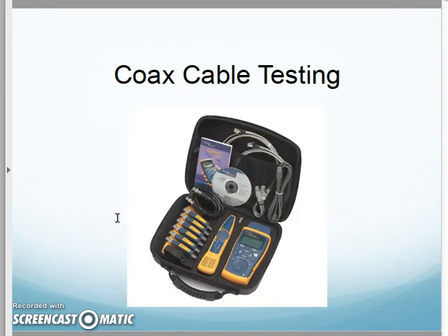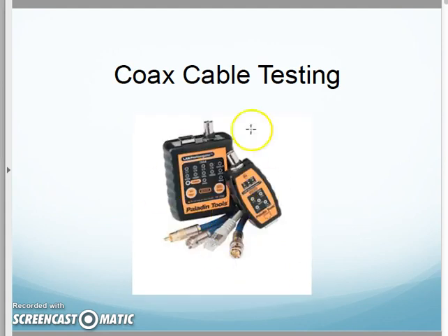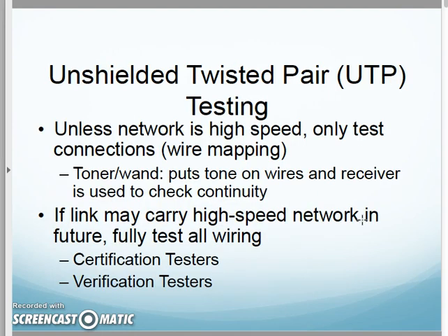The other thing we can do is there's actually meters, kind of like the wiremap meter that we were used to using in our lab, as well as our continuity meter. There's an adapter here for testing coax. We can use that to test our coax, so we can see if it is functioning, if there's any breaks in the shielding, any breaks in the conductor for proper function.